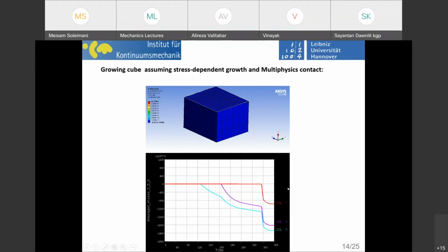It's very, very important. In plasticity, the outcome is that it crops your stress. That means that your stress remains bounded. This is very important. For example, if you are talking about crack propagation, at the tip of the crack, you know that from a mathematical point of view, the stress goes to infinity. But if you introduce plasticity, then plasticity makes your stress evolution bounded. So this is very important.